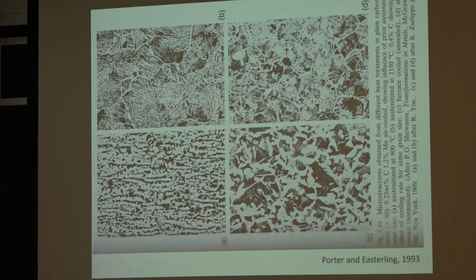And what happens during the quench, instead of what I call freezing the microstructure, there's so much driving force when you water quench or oil quench steel that you'll induce a transformation. It's not going to stay like it was. And that's why when you quench steel, it becomes very high strength and very brittle. These are the kind of differences in microstructure that you get.